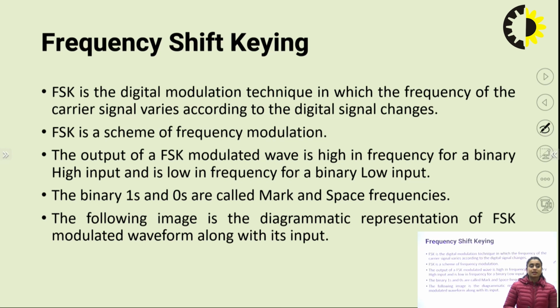What is frequency shift keying? FSK is the digital modulation technique in which the frequency of the carrier wave is varied according to the digital signal changes, right? Whatever digital signal input we have, corresponding to that, if we vary the frequency of the carrier, that kind of modulation will be called frequency shift keying. So it is a variation of frequency modulation itself, right? The only difference from frequency modulation, as we have studied in analog communication, is that here the input message signal is binary in nature and the carrier is a high frequency sinusoid, right?